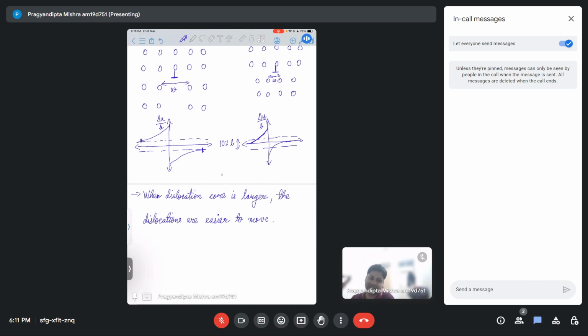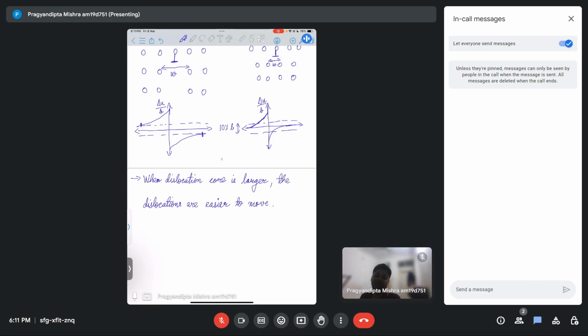So you cannot apply linear elastic theory within this dislocation core size, meaning that everywhere else within the material system the linear elastic theory is valid. So you can apply all those equations that linear elastic theory has in those other regions, but within this core region you cannot apply it. How this dislocation core width is decided, it is usually taken as 10% of Burgers vector, and that helps us to understand where the dislocation will be easier for moving or for gliding.